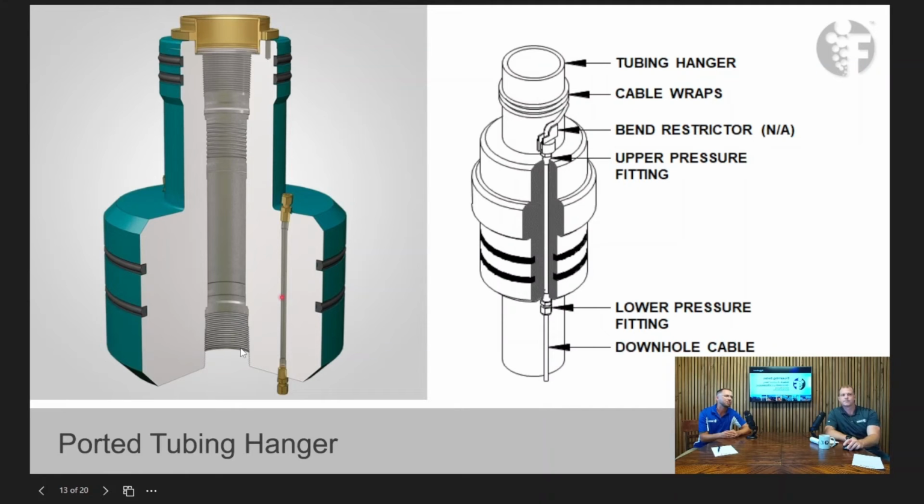And then another thing I'd like to say on the hanger on the right. This one over here? Yeah, I don't recommend that hanger. I know sometimes you have to run that hanger, but you're coiling that cap string around the tubing. You're talking about up here. Right. Yeah. And wrapping it, you're taking the chance of breaking your cap string. Okay, so you don't recommend this. You recommend just a direct pass through. Okay, that's good to know. And I'm sure everybody would hate to have to sit there and wrap that stuff. Man, I don't. Yeah. Well, that's good to know.